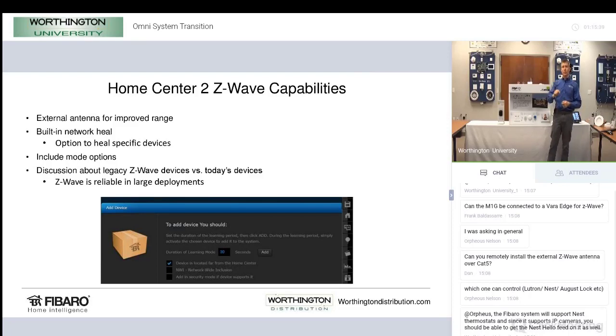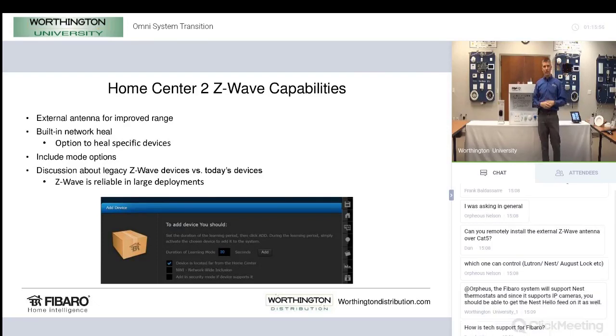And then there's one called security mode. Quick note is that there's a checkbox that says include device in security mode. You have to do that on locks because locks are the one device that really require the Z-Wave encrypted security. So if you don't, the inclusion doesn't go well. But in a recent firmware version, a little bit further down the list than we show on this screenshot here, you'll actually see a lock inclusion mode, which does that all automatically for you.